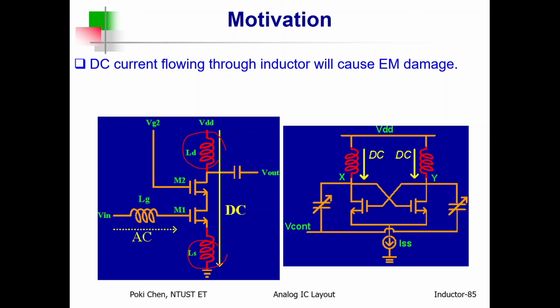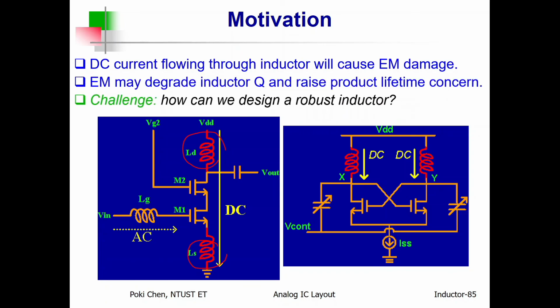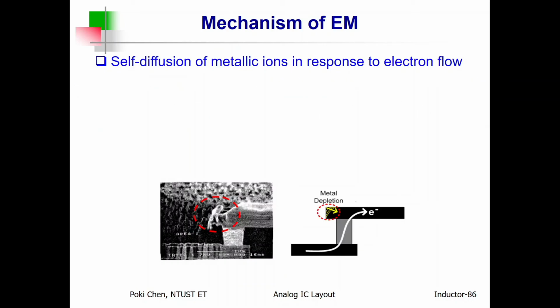Yeah, according to metal migration, which I told you about in chapter 4, the smallest chapter, but even though the chapter is so small, it still carries some very important ideas about failure mechanisms, right? So this is what they saw in the microphoto. They needed to figure out what was going wrong. And finally, they saw that the metal line actually became void here.